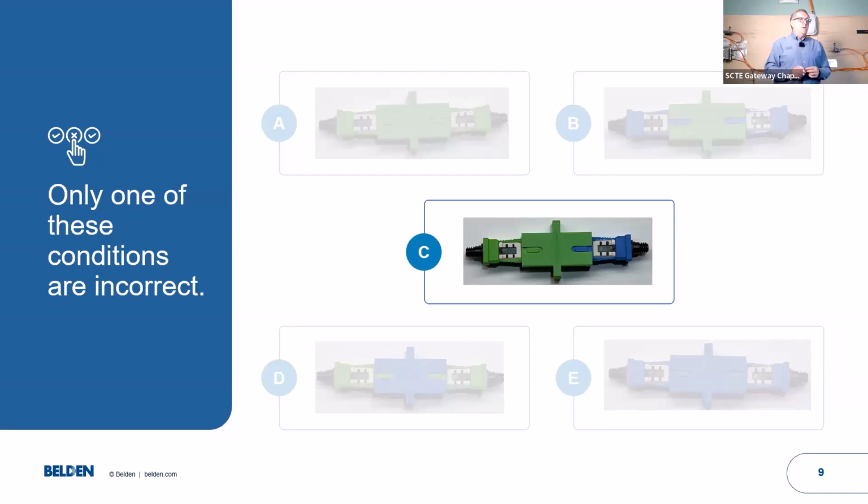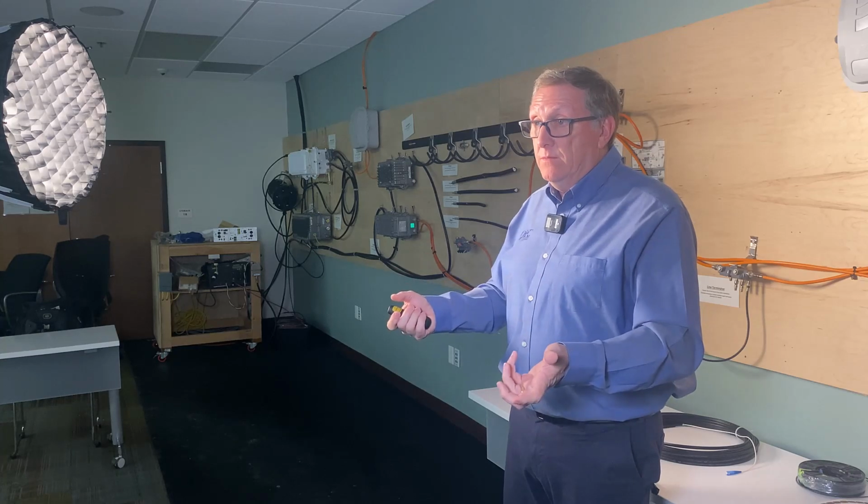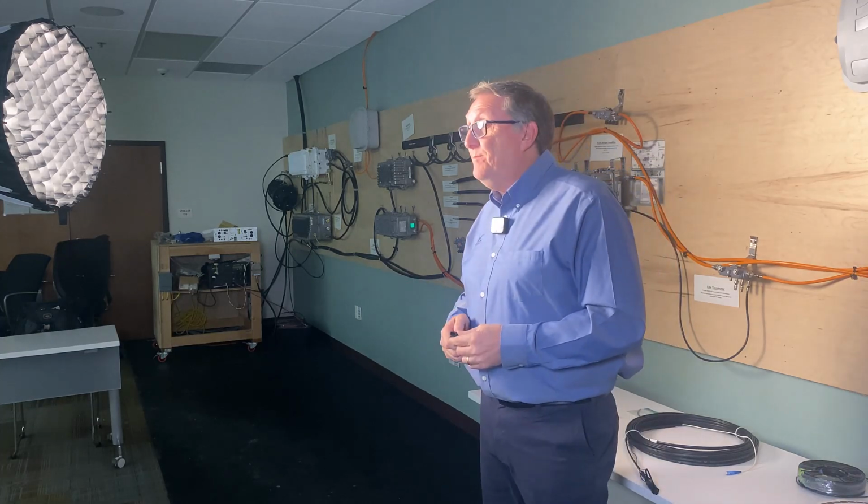And then the manufacturing tolerances, I assume these are probably cast. These are probably molded. Yep, plastic cast, die cast of some kind. If for some reason a manufacturing defect was there, you might potentially have too big a gap. And if there's enough of a gap, you're like, how could I be losing 3 dB through this bulkhead? Must be a bad bulkhead. But you take it apart, you clean it, you put a new one in, but it was dirt. Okay, cool. Thank you. You're welcome.